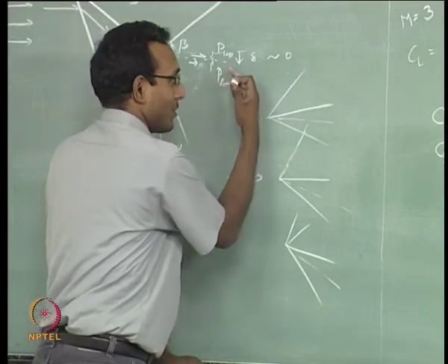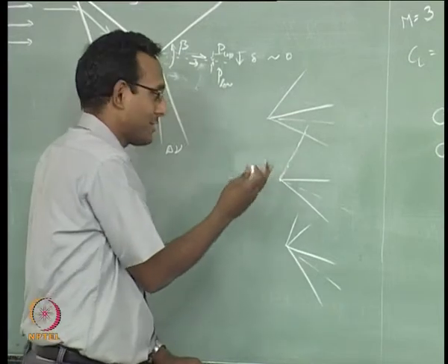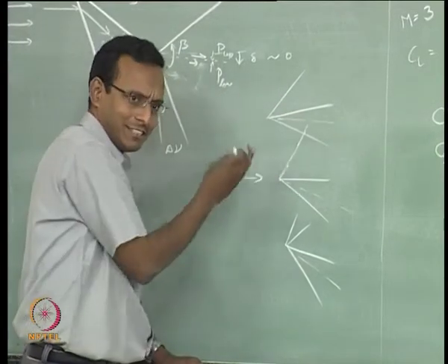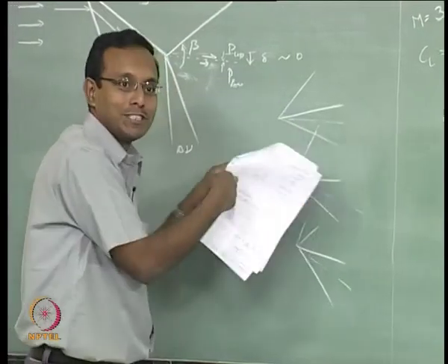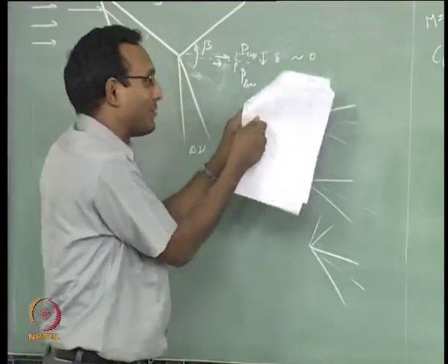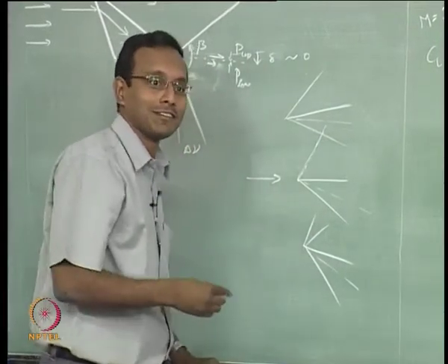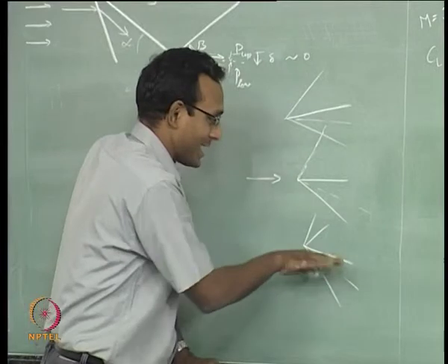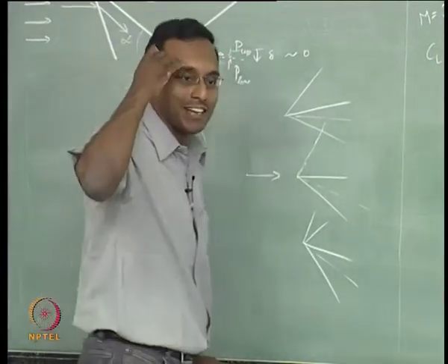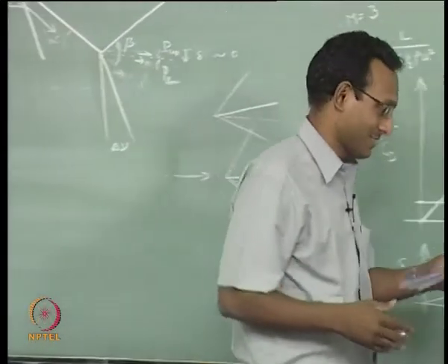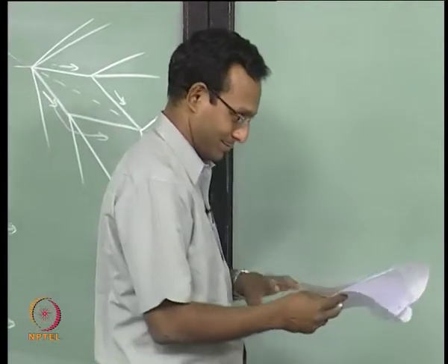The shock slowly becomes a Mach wave, that will be here. After that, that original Mach wave stays, there will be more and more Mach waves coming out, as if a fan is opening out. You know this Japanese paper fan opening out from one line, that is going to happen here. That is your expansion fan, they call it. So that is going to happen as you increase angle of attack. It is more fun to watch this. You should start feeling these kinds of flows. If you can feel that, then I have done my job teaching you this flow.